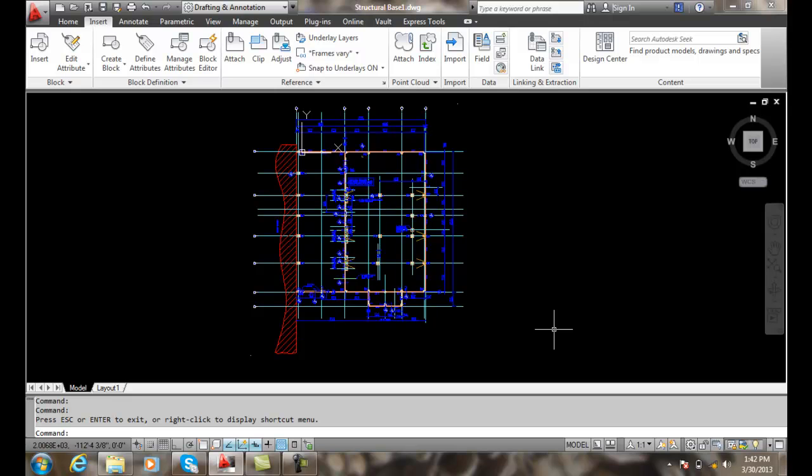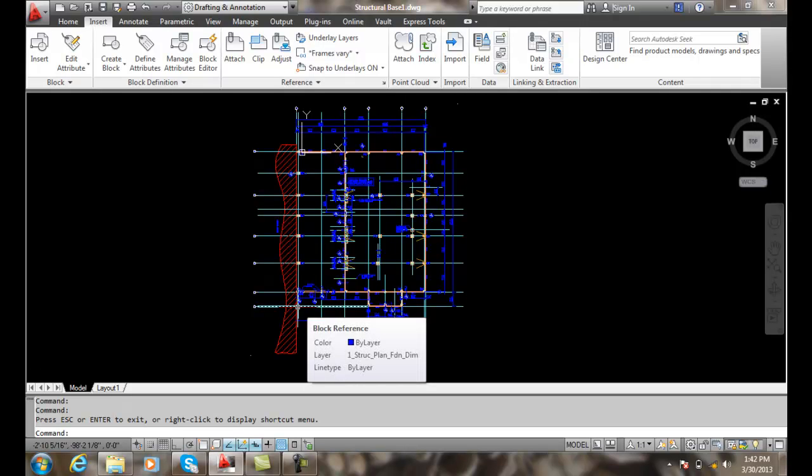If we don't do that, we just get stuff floating out in space in all the different drawings and nothing looks right. So we either have to draw everything based on 0,0, and that's ideally what we should do. But here's an example where my 0,0 is up here. You can see my X and Y is up here, and I wanted to put it down here at the lower left hand corner.